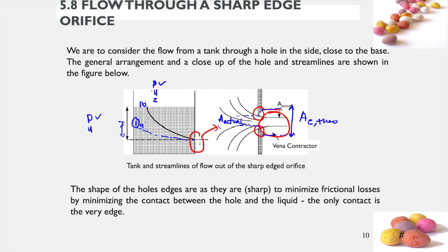Do we have velocity at point 1A? No. And another term is Z. If you are given the height from the bottom to point 1A, then you should have no problems solving Bernoulli's equation from point 1A to 2.